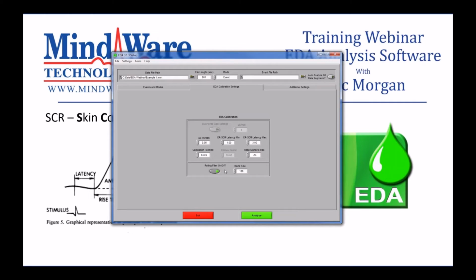And finally, we have the rolling filter. So I recently wrote a blog article on the subject. If you go to support.mindwaretech.com, you can see that. But just to summarize, the rolling filter is a rolling average defined by the block size, which is in samples. So what we do is we take a certain number of points or samples on the EDA signal, and we compute the average of those points, and then we plot a new point on the resulting waveform. And we proceed through the entire EDA signal in that fashion.